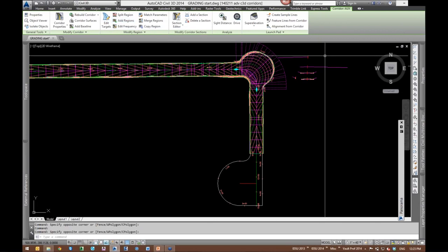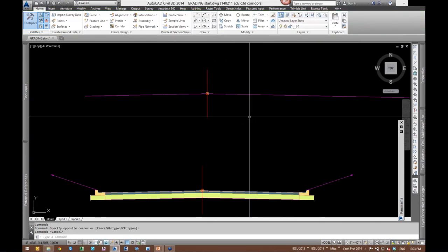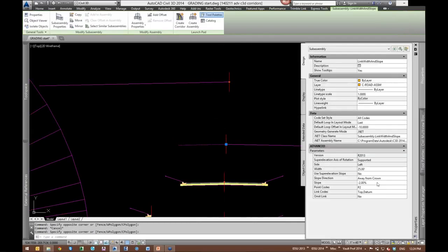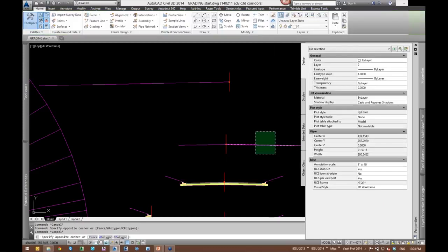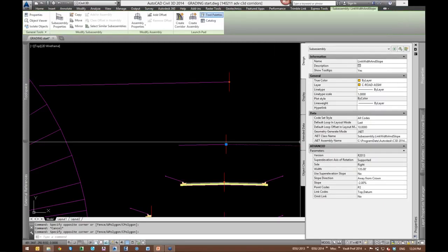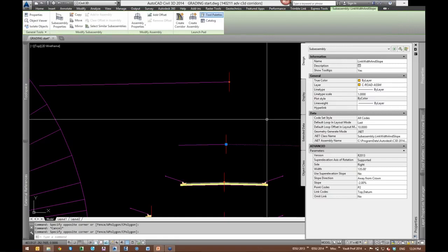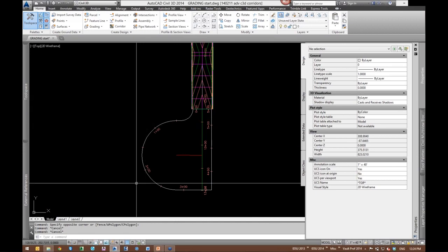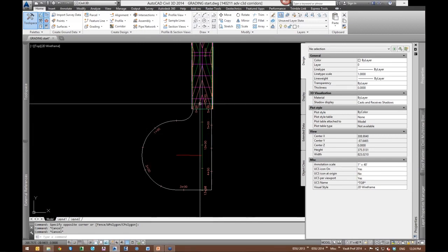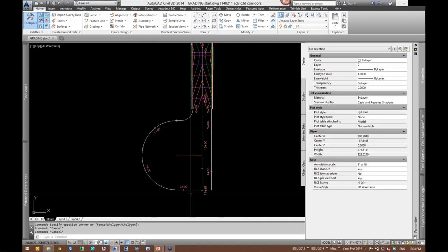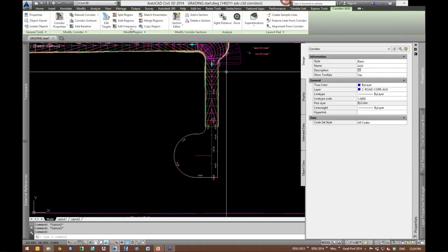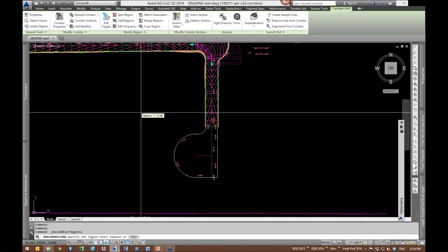Well, we've got a different assembly up here. And this one's quite simple as well. It's a link width and slope subassembly on the left side that goes at a -2%. That's 25 feet. And on the right side, we have -2% and 135 feet. And those numbers are nothing magical other than widths that get us beyond the flow line, or excuse me, the lip of gutter of this whole cul-de-sac. So we just need to get beyond that. So adding a region, we'll click Add Regions.